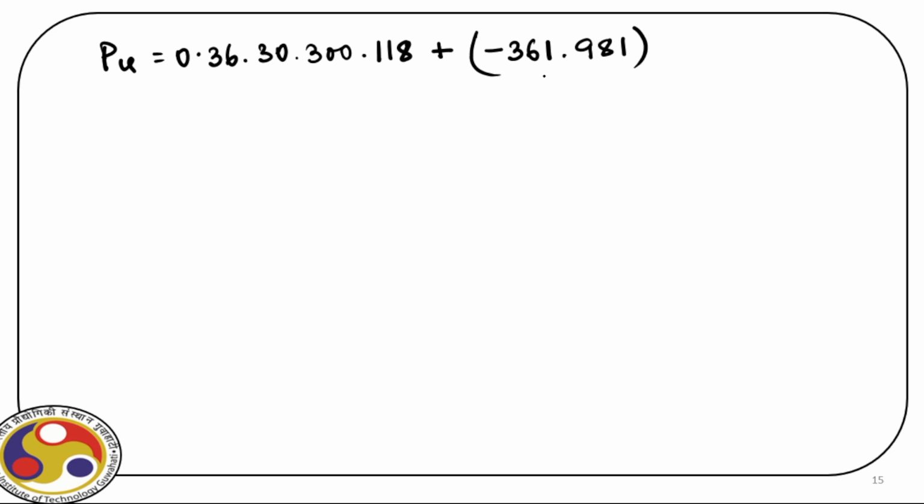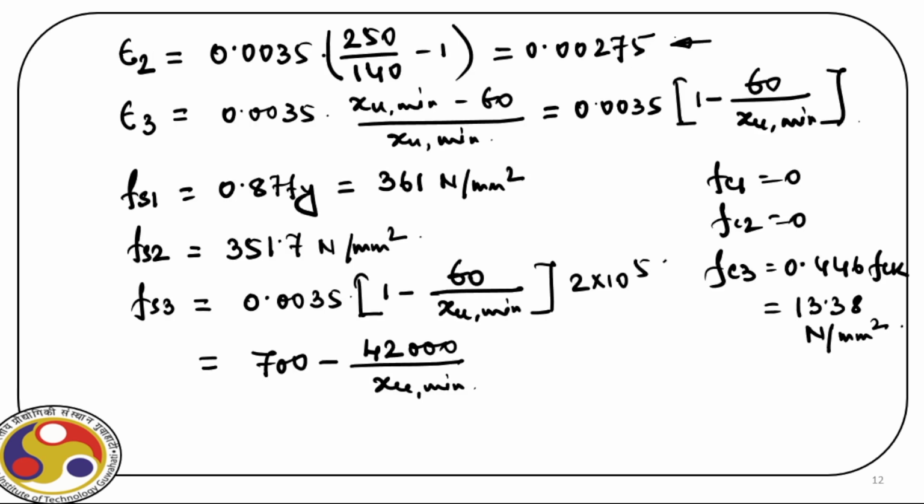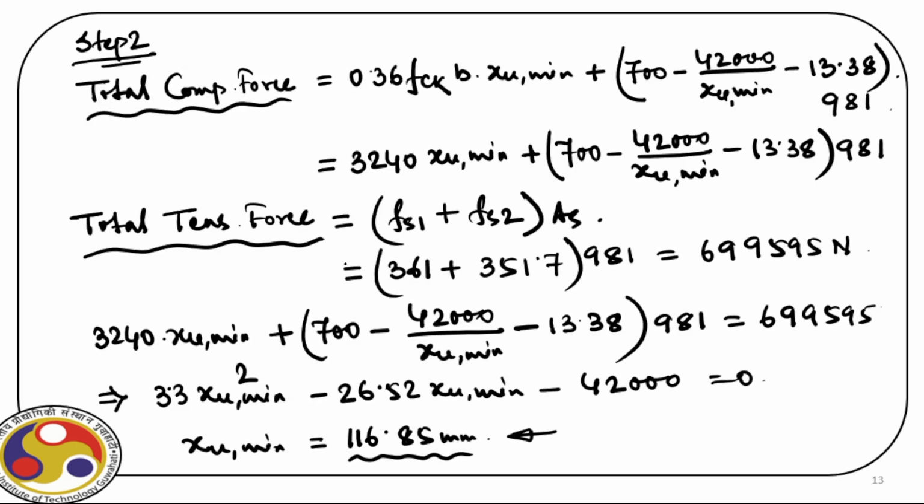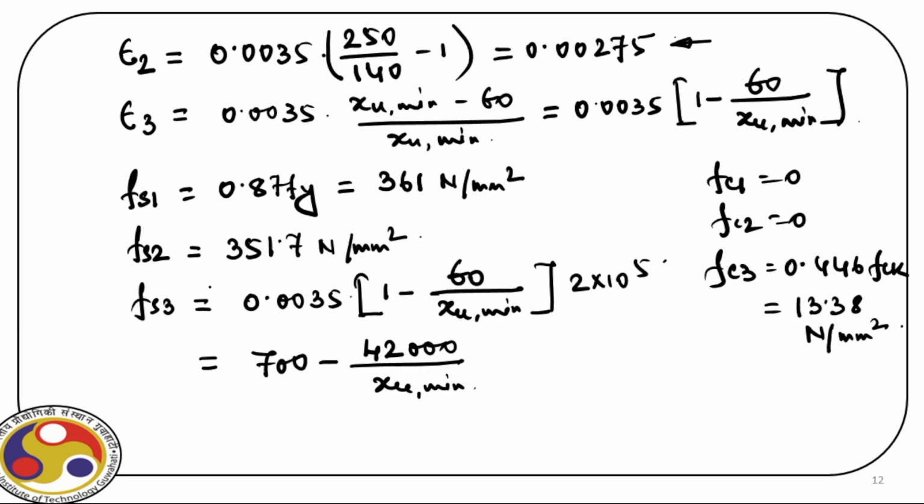Then this is from the first layer plus, let us use that value of Fs, what we did earlier, which is not exact because you have to figure out after this convergence, you have to again figure out epsilon 1, epsilon 2, epsilon 3 and corresponding stresses. So because it is close, let us use these old values and just cross verify. Leave that exercise for you. Exactly, you have to find out the value.